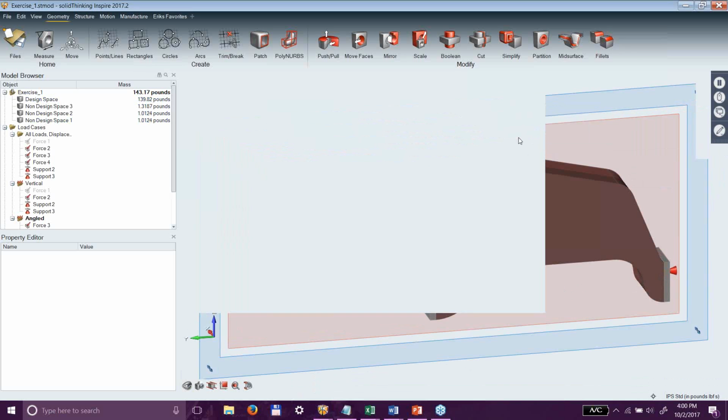Main limitations of Inspire over OptiStruct. Inspire actually uses OptiStruct for its analysis. The big difference is Inspire does topological optimization. It is linear, yes, linear only. Change element type in Inspire: you can choose any element type you want as long as it's a tetrahedron.